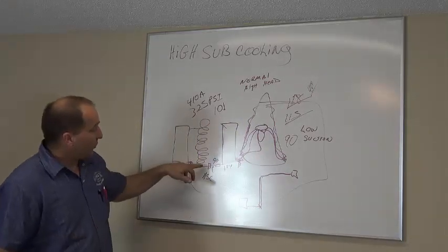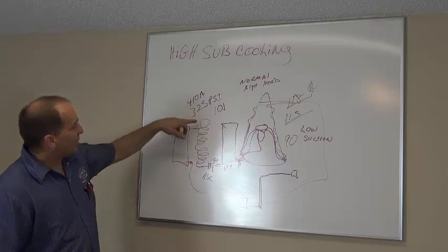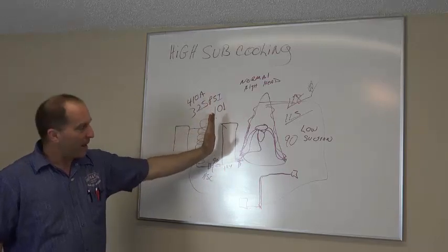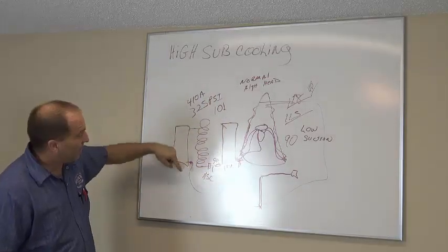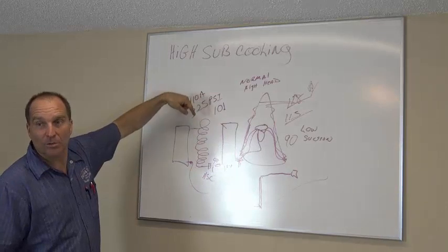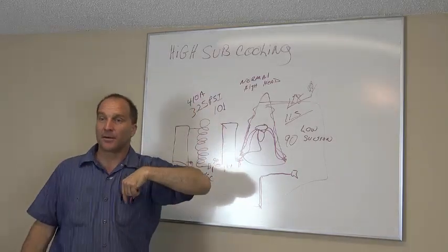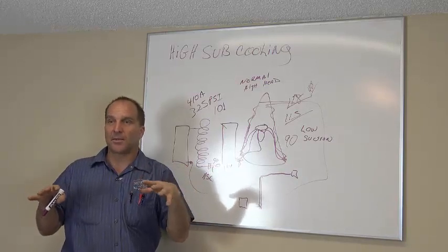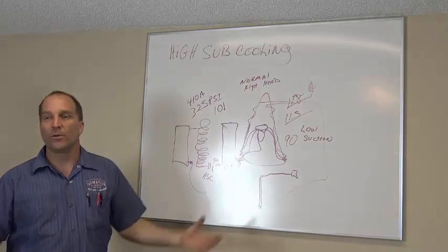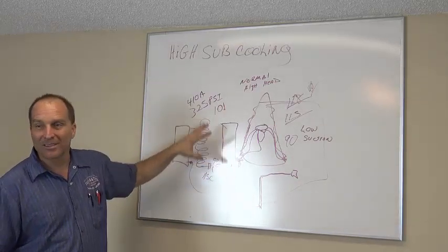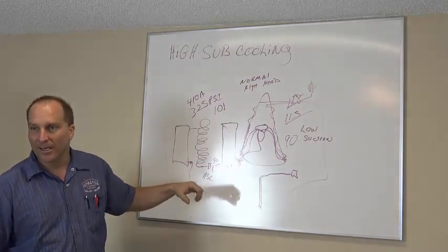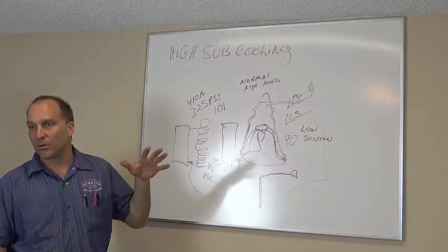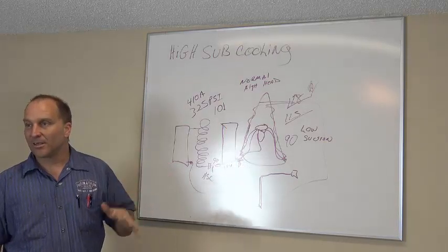So as he's putting refrigerant in that system, it sucks through that compressor, goes through the condenser, boom, hits that kink, and starts backing up, backing up into the condenser coils, right? What happens when it backs up, Adam? Remember them coils? The cars backing up at a stoplight? What happens? Airflow keeps going through the coils, right? And as the airflow continues to go through these copper coils, it cools the refrigerant down and gives you a larger subcooling.